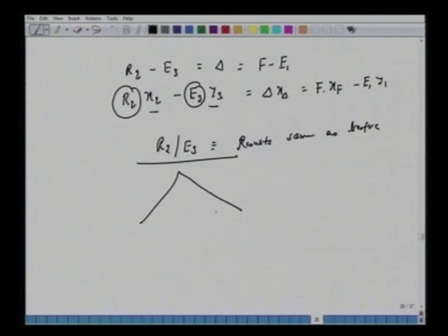But here we have made a point that if the question asked is only the ratio, then we should make use of this lever rule. Any operating line connects like this. The ratios of any points on this line between these two segments are in the same proportion as the amounts of the two streams here. Okay. So this example, the last example, is on multi-stage counter current. And all such examples related to multi-stage counter current rely on this location of del, the difference point. This is very similar to our distillations which we did earlier.